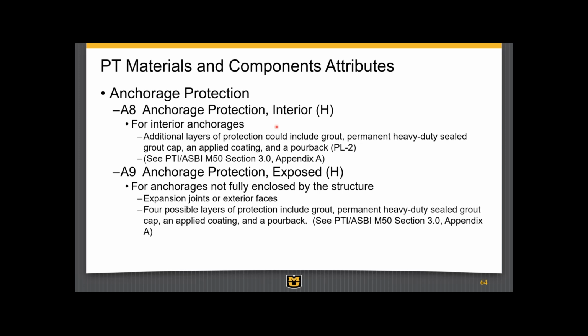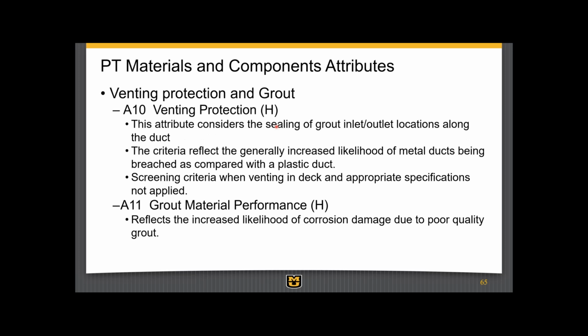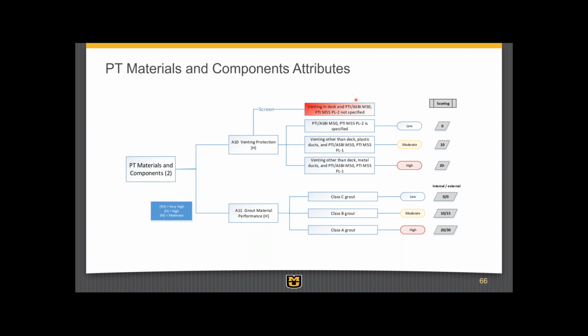There's anchorage protection characteristics, venting protection, considering whether grout inlet and outlet locations along the duct are sealed, and it reflects generally the increased likelihood of metal ducts being breached as compared to plastic ducts. That's in there. And it's a screening criterion when venting into the deck, and appropriate specifications for that are not applied. So that's another one with a particular screen. If it was vented up into the deck, where it has lots of exposure, you would assume exposure to corrosion products, water, moisture and corrosive agents, then that's going to be a screen.